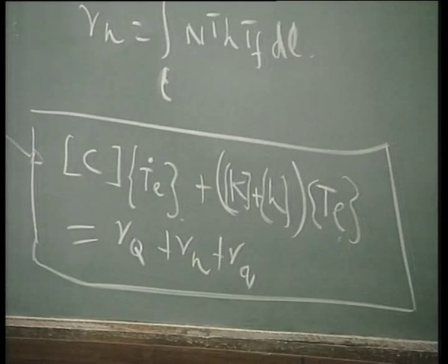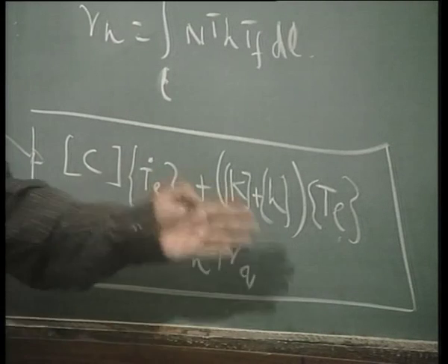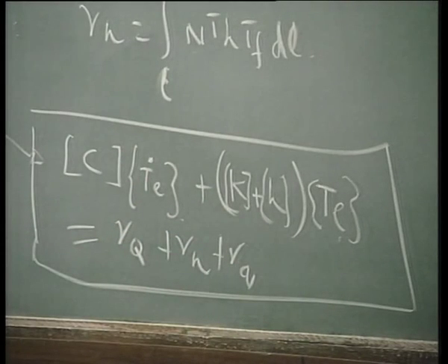Is there any question? Is it clear how we got this equation? We started with the differential equation, we formed the functional, substituted my well known shape functions and other things, then differentiated the functional with respect to T E, and ultimately collected these terms and wrote down different matrices, and ultimately got an equation of this form. Is that clear? Any questions?